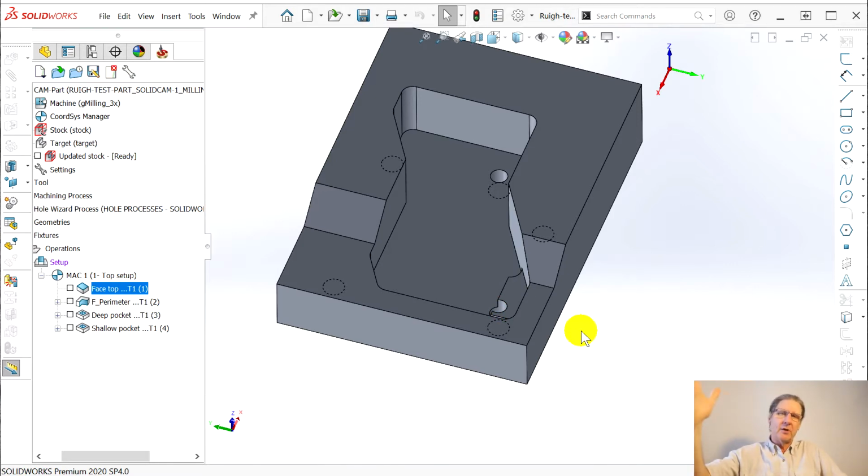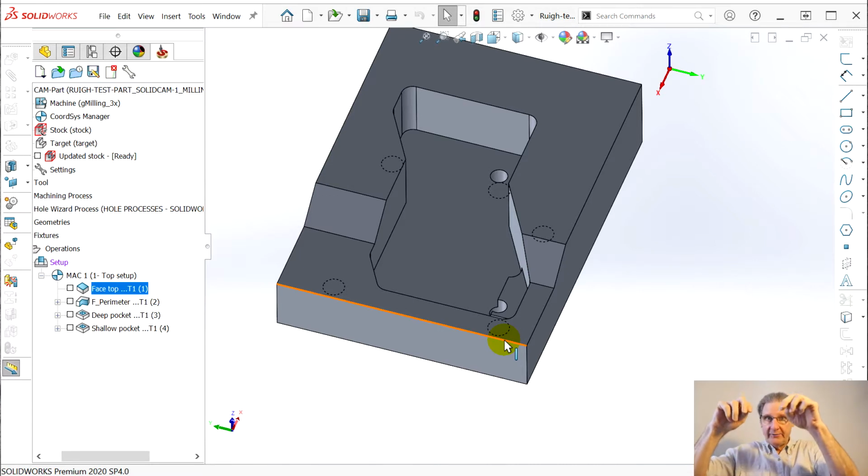See, I think if you just close that CAM part, it's also going to write to the file, no matter what. And this is maybe why I have this whole external business, where if you don't want to save the toolpaths inside your solid part file, you can save them as an external file, which is a zip file where they copy your original solid part, add a couple of things, throw all their toolpaths into that zip file, and then link them. So if you change that solid part, the original solid part that you're working on, which is now clean, doesn't have any toolpaths, nothing, small as it can be.